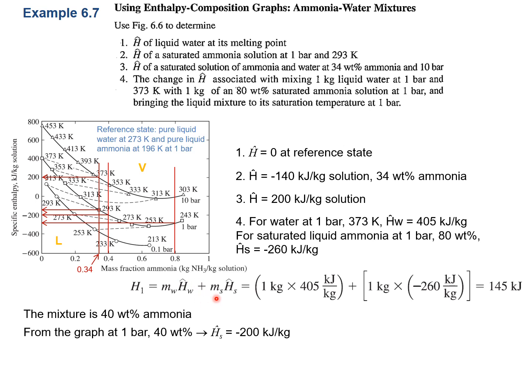However, the composition changes after mixing. At the very first time, 88% ammonia is there. 1 kilogram water plus 1 kilogram of the solution is going to 44% ammonia in the mixture. The composition of ammonia is going to be half of the original value because the mixture is 1:1. Then let me try to find the enthalpy value of this mixture.